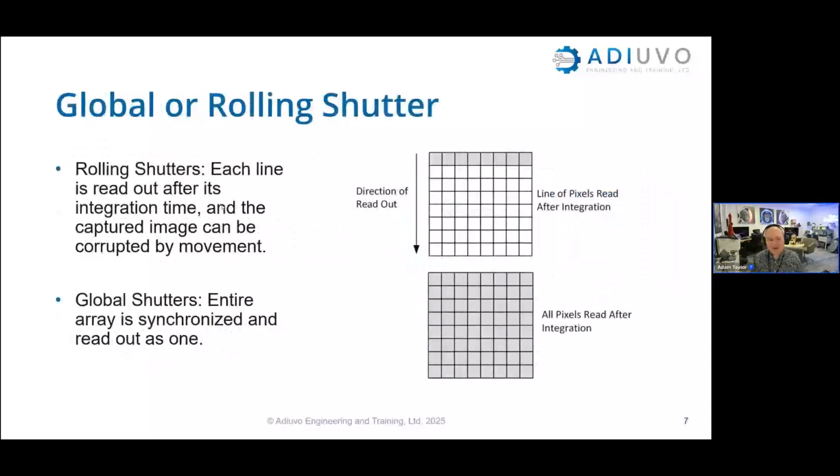The other interesting thing that we like about image sensors is how we actually read out the image. And you'll all have seen the great things that you can see online, and in the project there's a great link to this, where there's a helicopter taking off, and its rotor blades don't appear to be moving at all. The reason is the image sensor that's capturing the image is what's called a rolling shutter image. So that's reading out a line at a time from the sensor. It's not reading all of the pixels out at once.